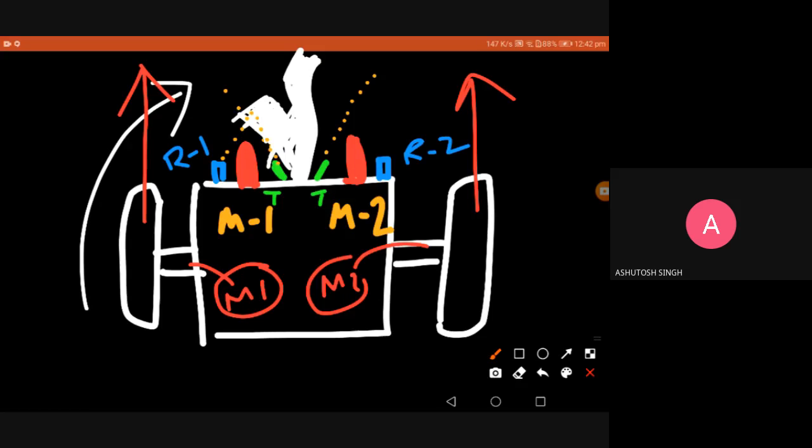Okay. So this is the simple idea of turning the robot. Whichever motor I keep off or brake, the relative velocity of the two motors is different. So the robot will slightly turn to the direction whose motor speed is less. You might have experienced this on a curve or bend when traveling in a car. When you're turning a curve towards the left, the right wheel has to rotate faster and the left wheel will be rotating slower.